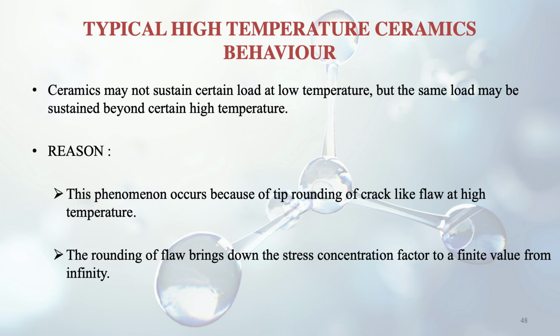Suppose it is a very sharp section, so it will turn into a circular or round form, and thus the stress concentration factor will come to a finite value from infinity, because in case of a very sharp section, the stress concentration factor is very high, up to the level of infinity. But as soon as we give a curve, like you must have read in your engineering drawing, if we give a fillet, then the stress concentration decreases. So a similar thing is here also: the rounding effect will decrease the stress concentration.